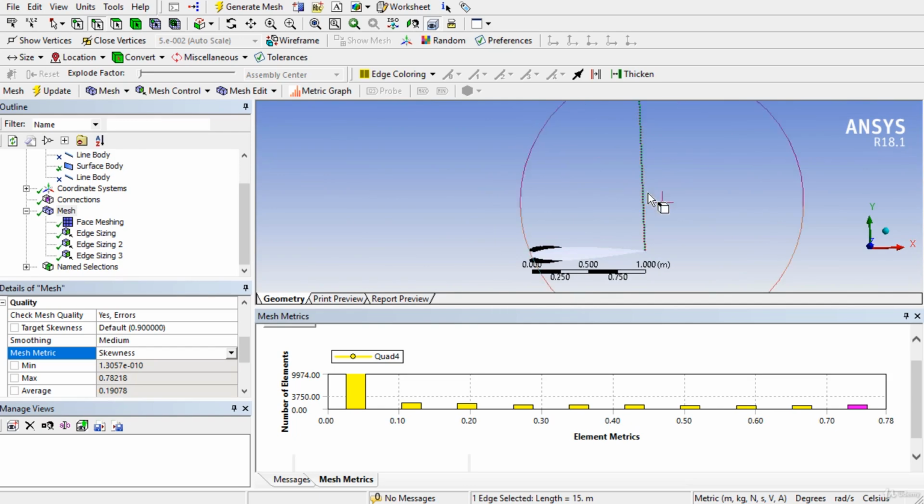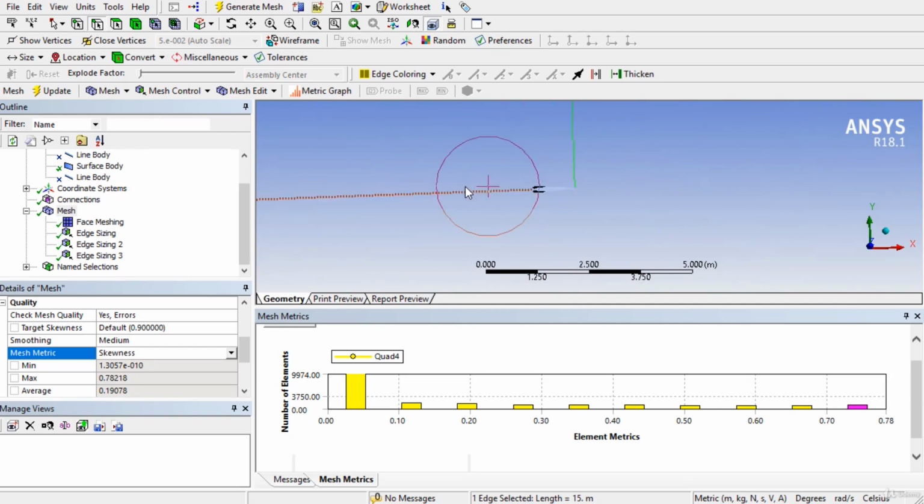Secondly, you can also subdivide the domain at some location near the aerofoil, and in a similar pattern we again get the C mesh, but this time we should be getting two zones. In one zone we can have a lot of control on the mesh distribution, and then we can open the mesh in the outer part. In this way also we can increase the mesh quality.